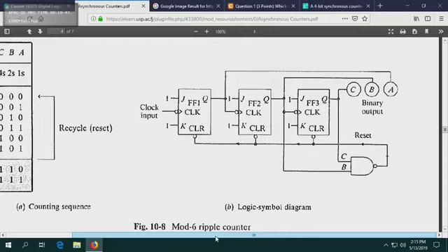Another major difference is that asynchronous counters generally we only use them to count in proper sequence, meaning 0, 1, 2, 3, 4, 5, 6. Doing random numbers is possible, but very, very complicated. Like if I gave you the problem in asynchronous, by now you guys have mastered the synchronous problem because you did such a large project with all the different numbers, so many gates to draw, so many Karnaugh maps.